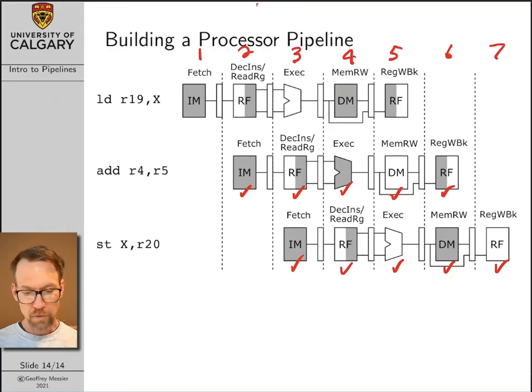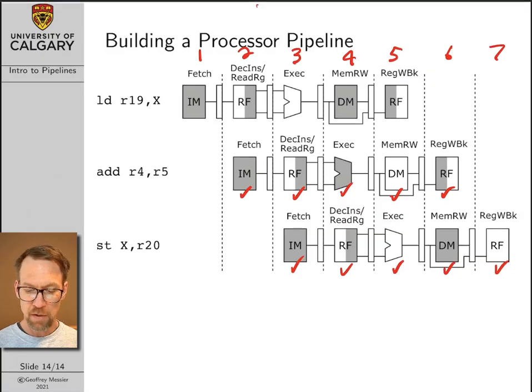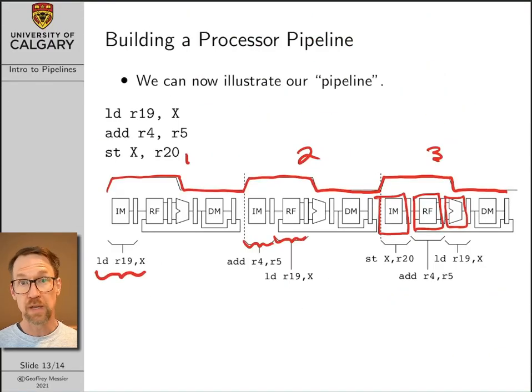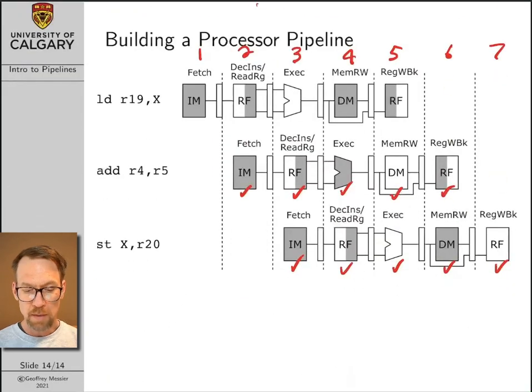So, again, go through this slowly. If you need to, pause the video, rewind, make sure that you're comfortable that what I'm representing in this diagram is the same thing that I was representing in this diagram over here. Remember, this diagram is not meant to imply that we have 3 parallel data paths physically existing in hardware. This is the same physical data path. We're just representing it one time for each instruction that's propagating through our pipeline.